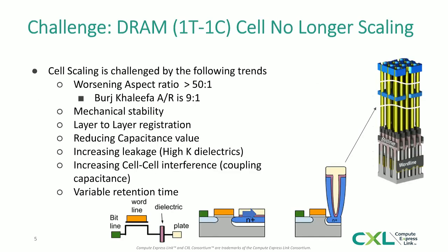So next, I will speculate on why memory cost per bit is not dropping anymore. And for that, I'll bring up the picture of how DRAM works. Basically, it is a charge storage device, a capacitor. The capacitor stores charge that indicates whether it's a 1 or a 0. In the good old days when planar technology worked, the transistor and capacitor were both on the same plane.